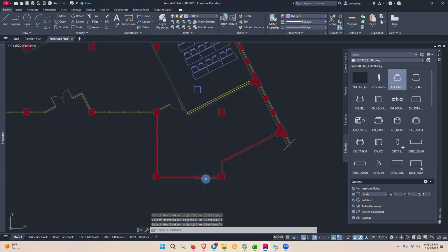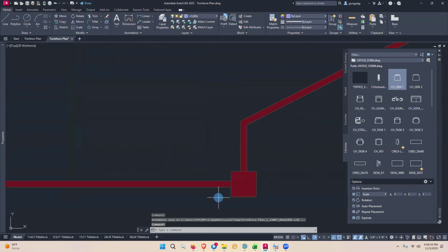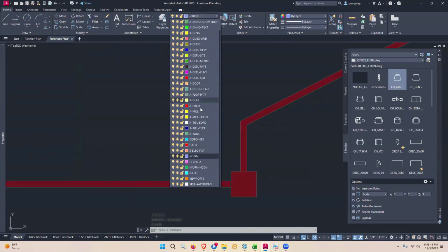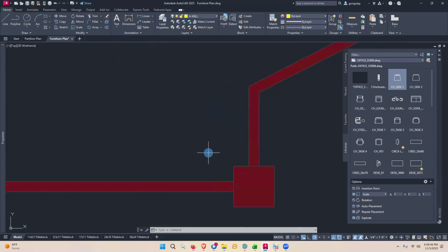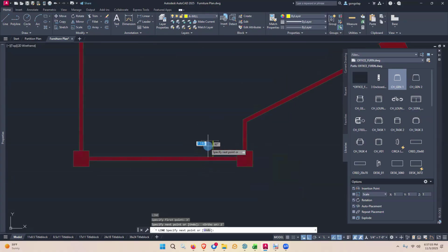All right. So let's look at the kitchen here. So I've got a refrigerator that is going to go here, and then I'm going to have millwork running along this wall here. And the refrigerator, I think what I'll do is I'll just make this, oops, let me go on to my millwork layer here. I want to leave, I don't know, probably 3 feet. So I'm just going to O-track over 3 feet and then go straight up. I'll put my ortho on for this. I'll go up 2 feet for the cabinet. A base cabinet is 2 feet deep, virtually always.